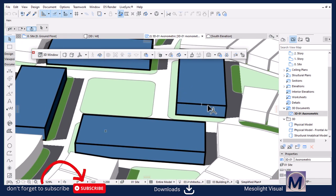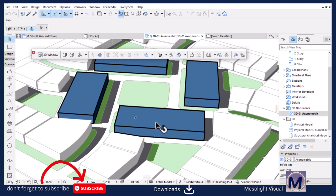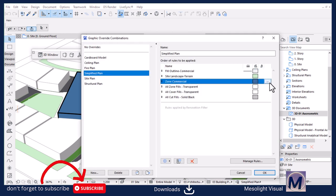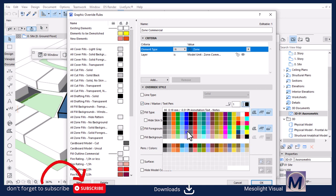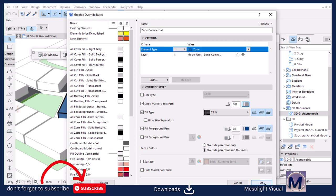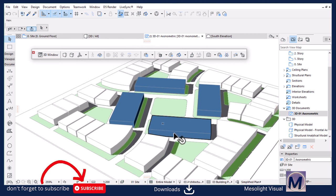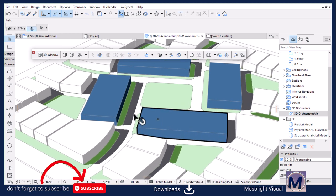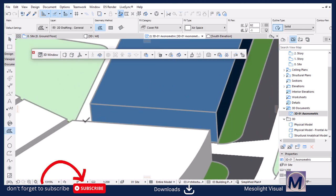But now, you see, these lines are also affecting the results. So what I'm going to do is change the line type, the pen for the commercial plots under the zone commercial rule. Let's edit it, and then I'm going to overrule the pen and set it to 0.13 as well. Yes, perfect. Now we have a nice outline around that is not competing with the edges of the commercial plot.